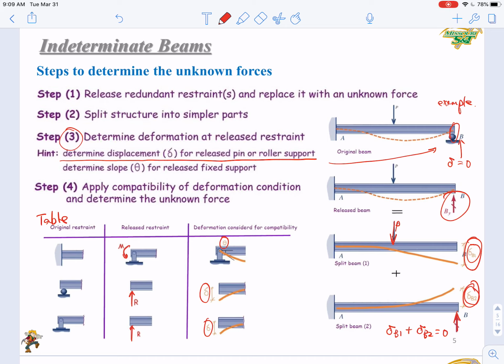That is to say, if you want to solve the problem from the fixed end A, the additional equation that you can write can be the slope. You can focus on slope, since at the fixed end, no matter how this cantilever will be bent, the slope at this point will always be 0.